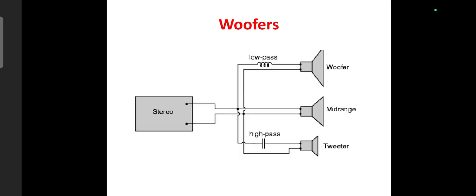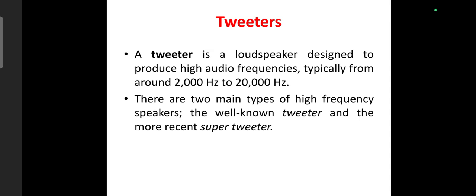The second is tweeter. Unlike the woofer, the tweeter is designed to produce and reproduce high frequency sounds, generally about 2 kHz and above. These include human speech, violin, flute, cymbals, birds chirping, and other soft sounds. Since high frequency sounds require only small air movement, tweeters use a small and lightweight diaphragm, enabling them to vibrate extremely quickly and reproduce fine sound details accurately.